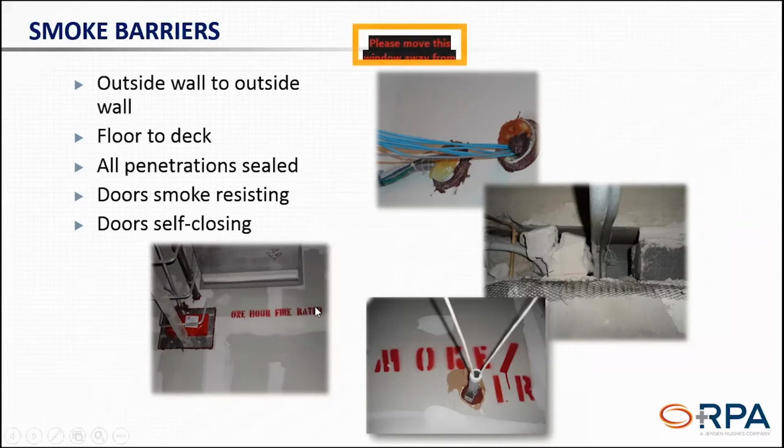Sometimes we see our walls stenciled. That's a good thing. That tells whoever might be coming up to run piping and things that they need to seal up their penetrations, except when they don't follow the rules and they just poke a hole right through your stencil and don't end up sealing it up.